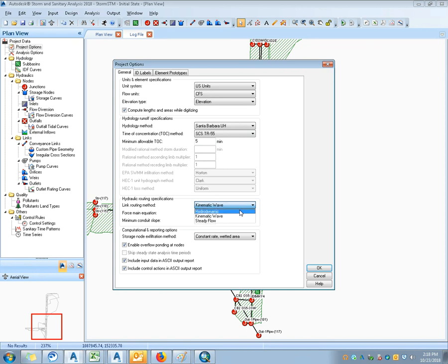I pretty much always think this hydrodynamic works better. If you just have a single span of pipes, you don't really need to worry about it. But if you have any sort of flow coming in from different directions, some sort of pond, you really want to run hydrodynamic.